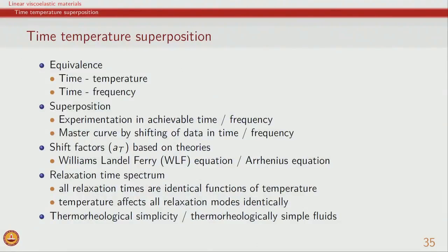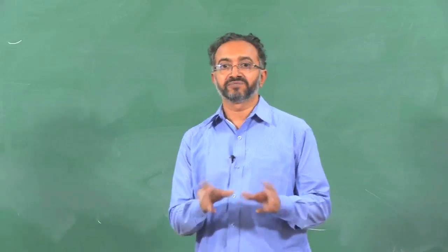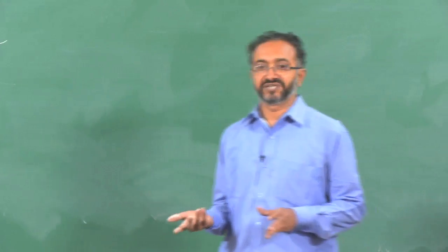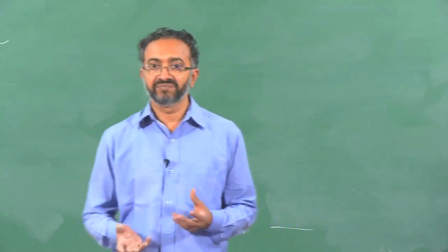What we have done is exploit the idea of equivalence of time and temperature, or time and frequency, because by changing temperature we modify relaxation time, and by changing experimental time we also perturb the material at different time scales. So both can be used.